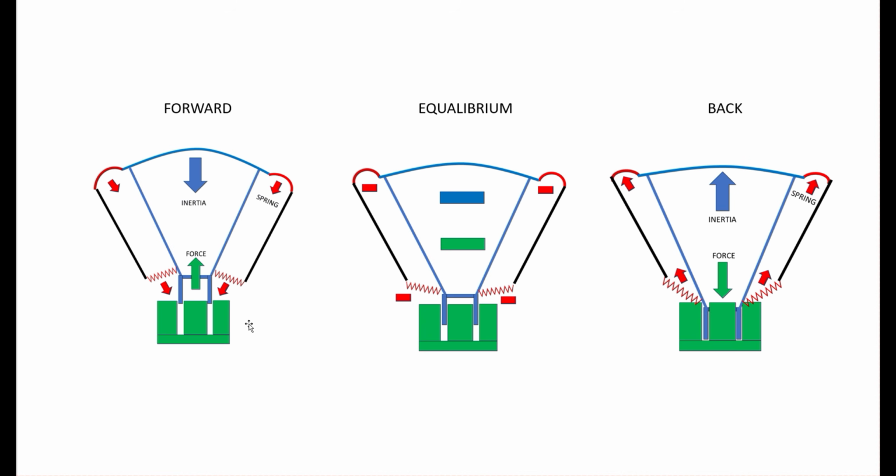Now, when we push the speaker forward, so the motor drives the voice coil forward, which pushes the cone forward, it will stretch the suspension of the speaker, right? Stretch it out like a spring. It'll get to a point where the spring goes, okay, that's enough, and starts pulling the cone back towards its resting point. It naturally wants to pull because it's like a stretched spring, right?